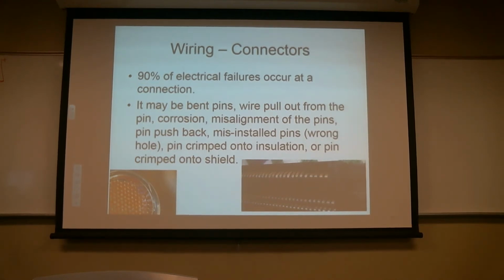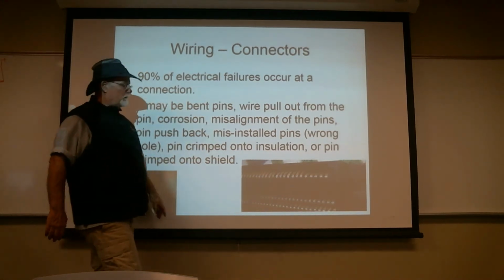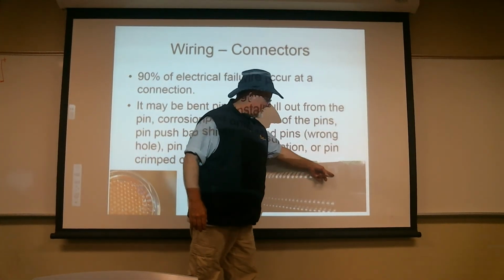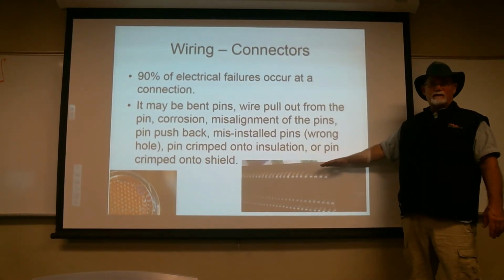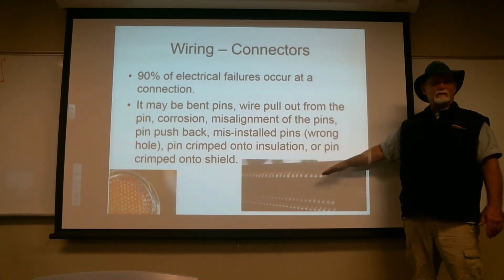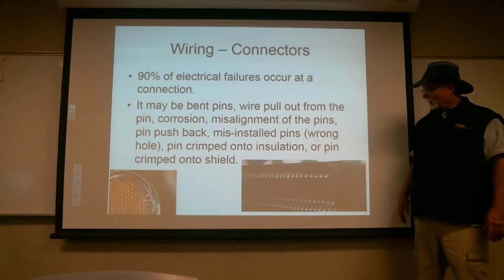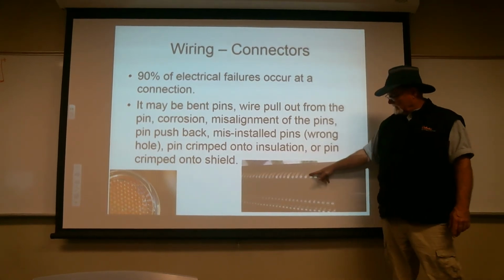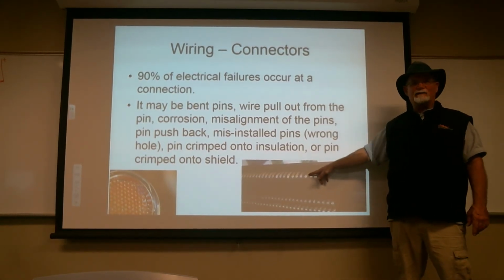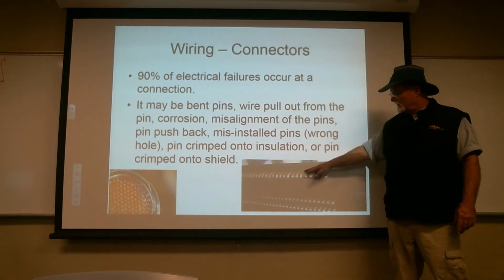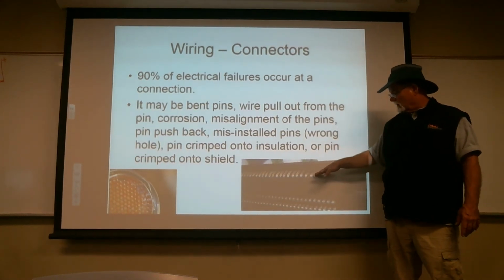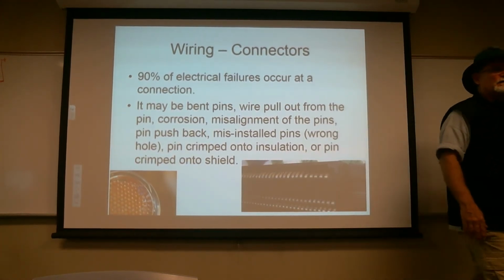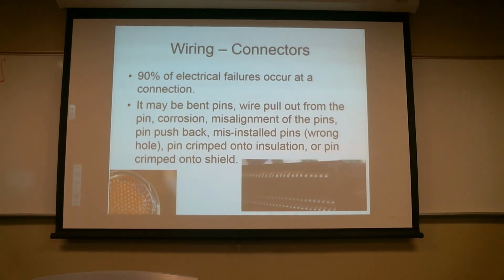Another example of the spring pad type, here's the kind where the wire pin comes in and wraps around and lays flat against here, and then there's a board that slides in. And this is very much like your USB connector, only much more grandiose. And of course, in here you can see somebody stuck something too big in there and it flattened these guys out big time. These guys still have more than enough spring tension to flex against the board, but somehow or another those guys got mashed flat. So those are going to be intermittent connections, not that good.